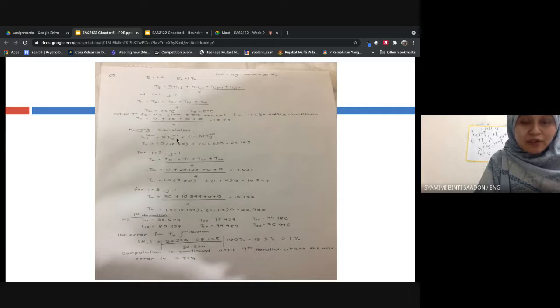And then we apply the over-relaxation just now, 1.5, to differentiate the values of new and old value. So we have the new value of T11, this is the new value 18.17, and so we have 28.125 by using this over-relaxation. If it's given, then we just use it. So we have T11 28.125.